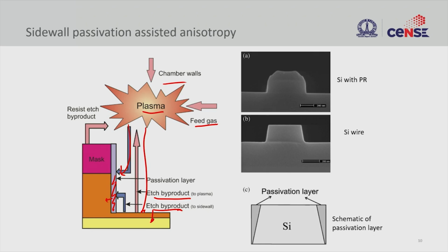And the resist is also participating in this whole reaction, right? The mask, the photo mask that we use, if the material can be etched with the plasma that we generate, ideally you don't want any reaction, but we never get infinite selectivity, right? So the material selectivity, let's say 1 to 100, right?